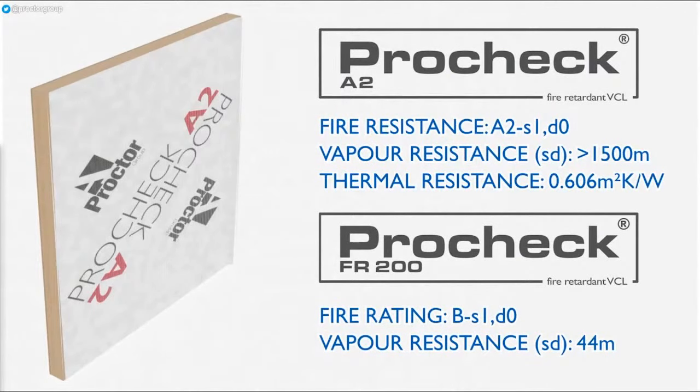This gives ProCheck A2 a unique additional benefit of a low emissivity surface, which when used with the service cavity can enhance the overall thermal performance of the construction, as well as providing high fire performance with its A2S1D0 fire classification. ProCheck FR200 is used as a fire retardant vapour control layer in roof and wall structures in new build